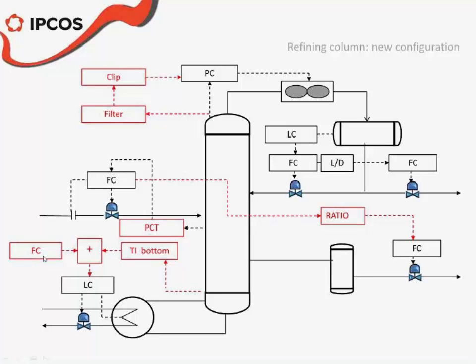on this flow here, which is the steam flow coming to the reboiler, and we also were looking at the temperature, at the bottom temperature of the column. If it was too high, it was probably because too much heat was being put into the column, and then a correction was done on a feed-forward action.